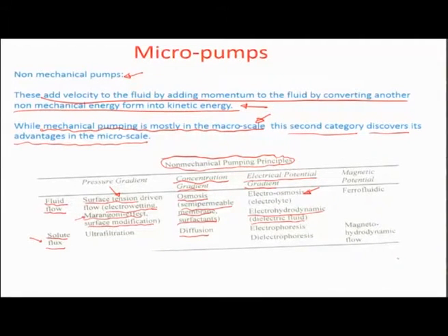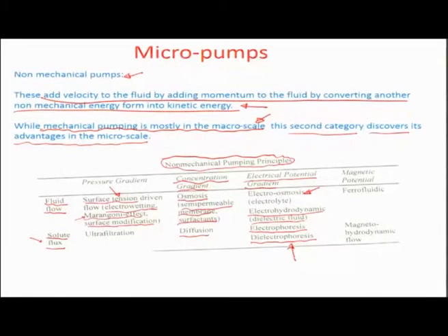So, there is also the electrohydrodynamic principle, which relates to a dielectric fluid which is being pushed into one particular zone of a flow stream. There can be electrophoresis, where there are charged particles migrating within fluid flow, which are again driven through an external field, and then finally dielectrophoresis, which is because of the change in the electrical permittivity of the medium with respect to, let us say, some particles or a second phase, for example a gas within a liquid, because of which there can be migration towards the lower electric field zones from the high electric field zone. So, these are different electrically applied gradients where potential difference would be the cause of movement for, in some cases, solute flux to happen, or in some cases fluid flows to happen.